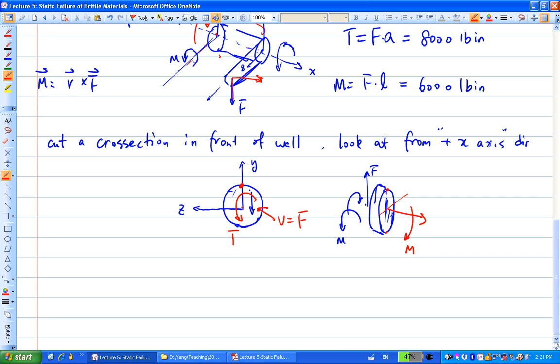Okay, and this shear force V will give you a shear stress, and shear stress is always maximum at the neutral axis location here, but 0 at the top and the bottom. So in other words, this location here will be a critical location. What we're really going to look at is just this location and this location, because both of these give us a maximum due to the loading condition. Which one is more critical? We have to make a conclusion after the calculation.